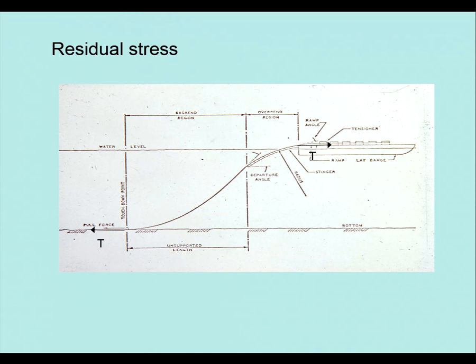So I've got M product acting down there, which equals the area of the product times the density of the product. And if that's an oil, stabilised crudes are typically 800, 850, something like that. And if it's gas, 160 kilograms per metre cubed. So these are all masses.